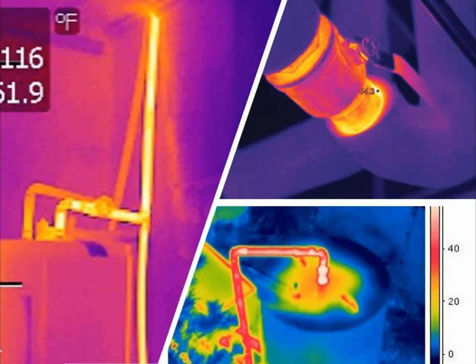And just to prove that fact, here are a few thermal images of pipes surrounding hot water cylinders, and some, like in this case, the top right over here, a shutoff valve, which is not necessarily close to the hot water cylinder, but probably part of a hot water line or a primary loop. And you can see from that, all arguments that heat loss through pipes is insignificant fall away completely. You do lose significant amounts of heat through pipes, and I will just reiterate the fact that you don't need flow through the pipes in order to lose the heat. It's not only when you're using hot water.